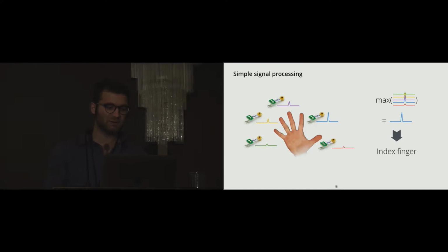The device is coupled with a low-level interaction monitor that detects interaction events such as touch events or key presses. To identify which finger has been used, we use a simple algorithm that examines which vibration sensor created the highest voltage right before the event occurred.